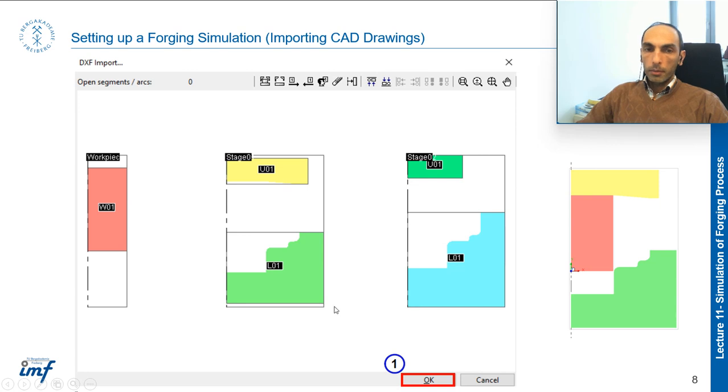But usually for forging, not all the time, the part has axisymmetry, so you can simulate it in 2D. If you can simulate in 2D, it's better to do so and not simulate in 3D, unless you have some reason for that.